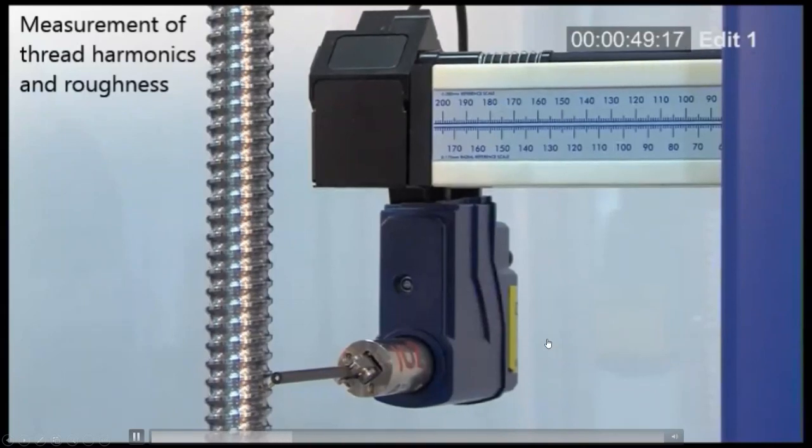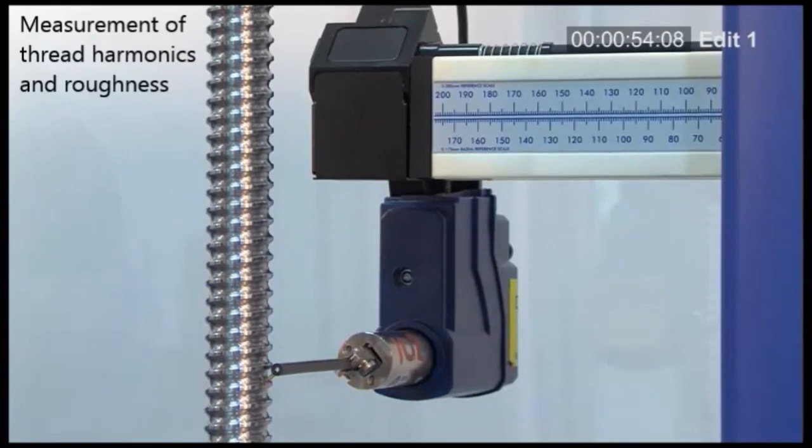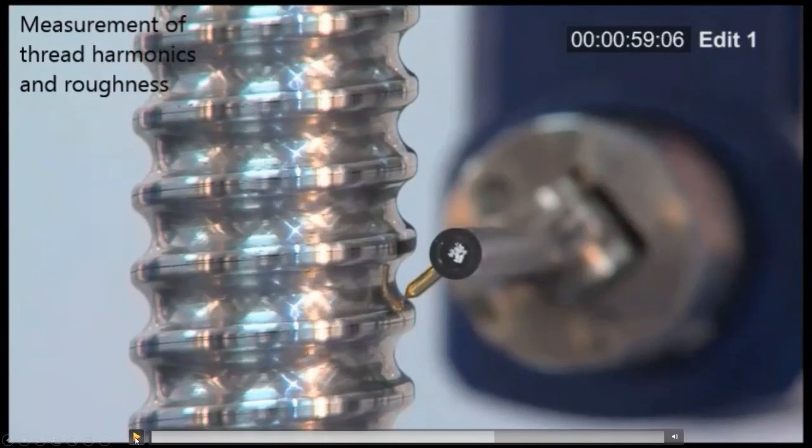So we're measuring the thread harmonics, the measurement of the harmonics around the helical shape here, and the stylus tip there is a 5-micron conisphere diamond tip, and we're keeping on track at a certain point around this track. This is the contact point of the ball bearings that sit in here, and there's one on the upper surface as well. If we measure them separately, the lower track and the upper track, it means that we are able to better define where the errors are coming from.